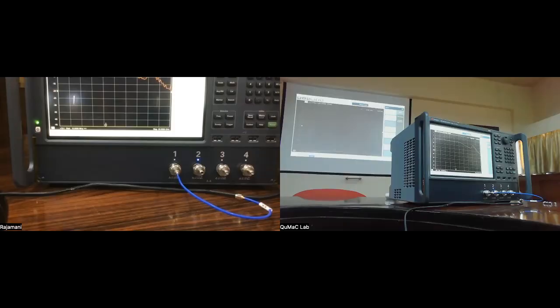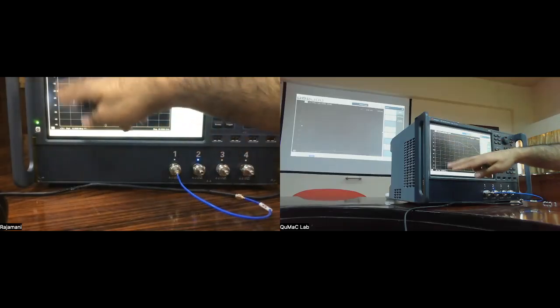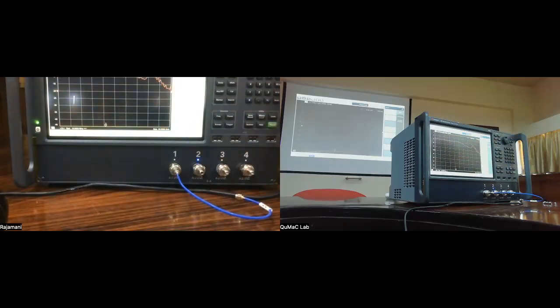This does not mean equal. So what it means, the m here refers to 1 milliwatt. That's the reference power. But this 0 dBm means it's an absolute, it's 1 milliwatt. 10 dBm would be 10 milliwatt. Minus 10 dBm would be 1/10 of a milliwatt. Okay. So this is not dB, it's dBm. Everything else we have been talking about, so the y-axis here, which is measuring the transmission in dB, that's dB. So that's just a ratio.